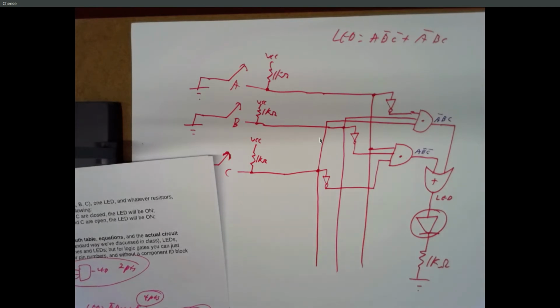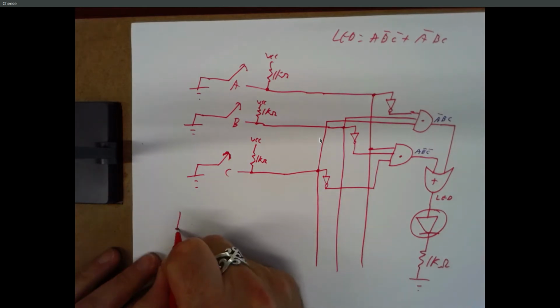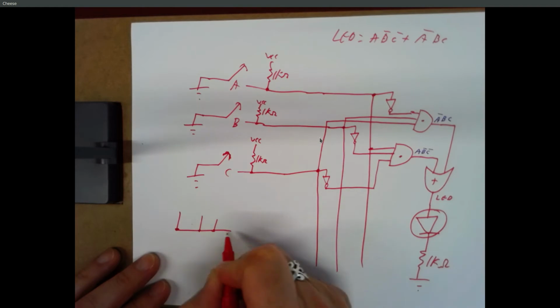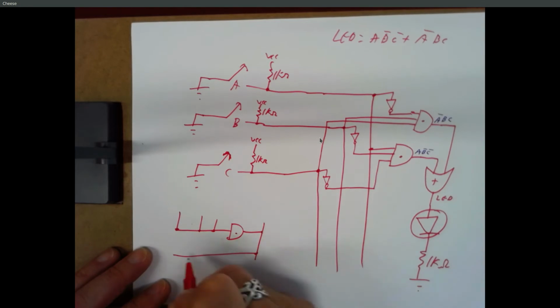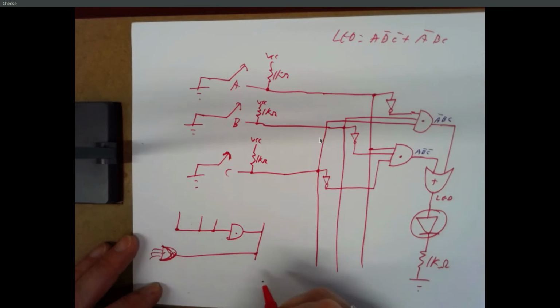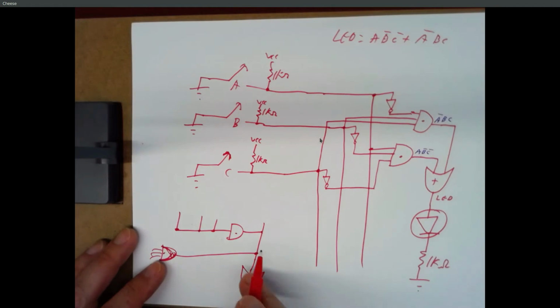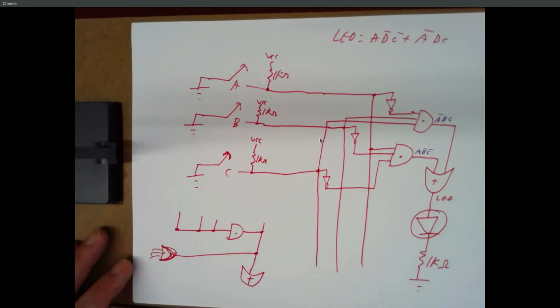What else? And don't draw this the way we draw fuse maps, right? This is technically not a valid circuit. Right, this has got the output of 2 gates wired together to each other, and this has got 3 switches all shorted together on the same line going into an AND gate, right, a 1-input AND gate.